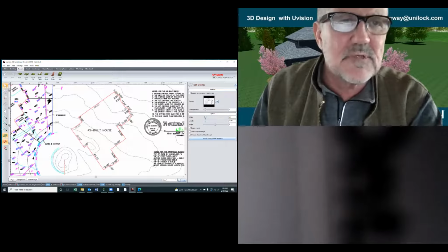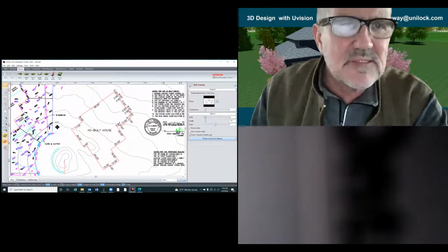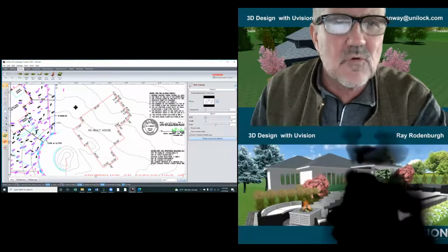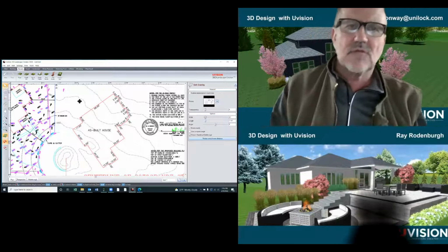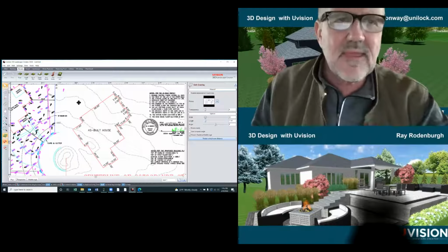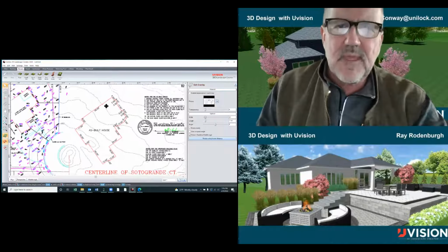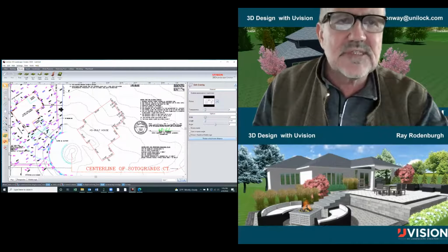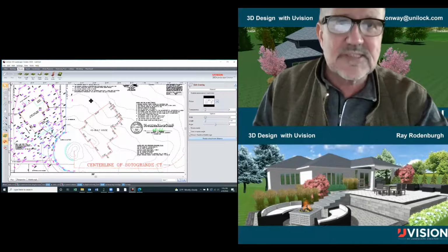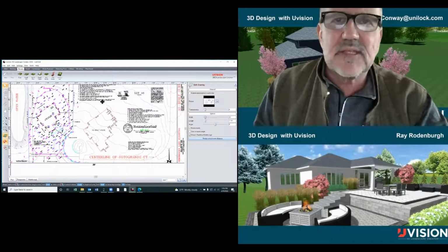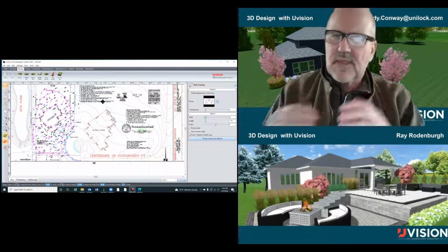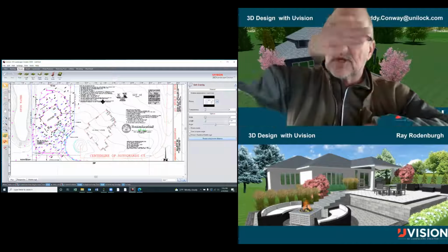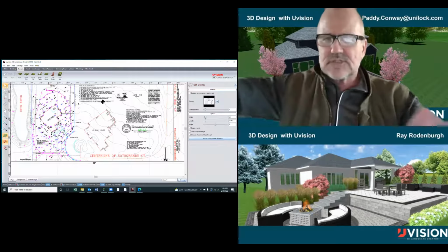You see the number 680, 681, and 682. That tells me that the contours are being read in 1 foot intervals. And by that, I can assume this 680 drops to 679, 678. So this was designated when they were laying it out in 1 foot intervals. It's not a big jump, it's a nice level slope.